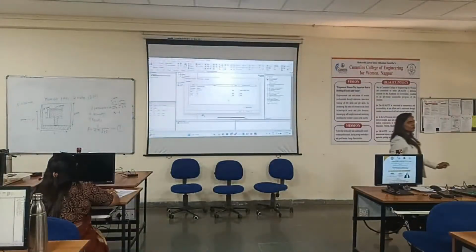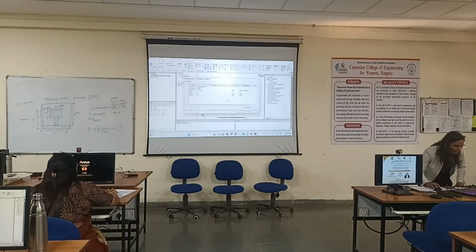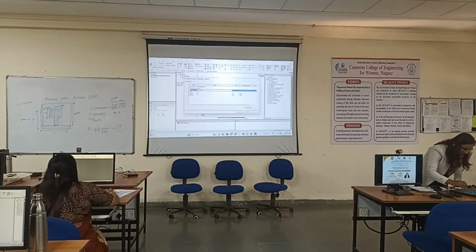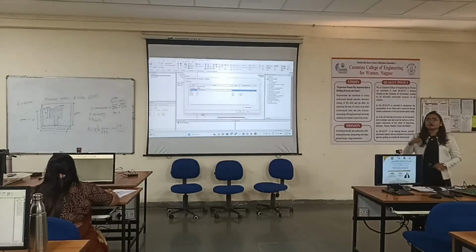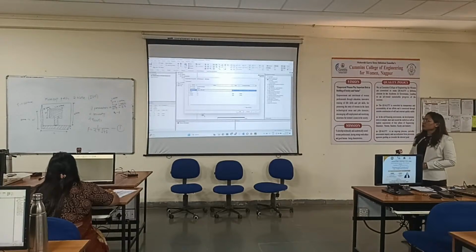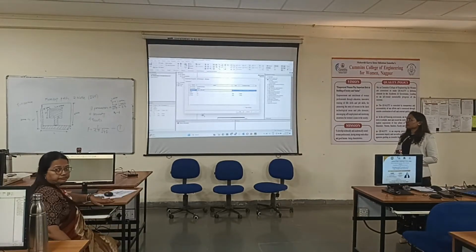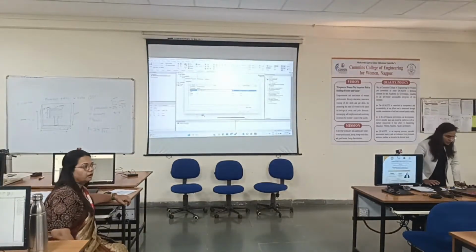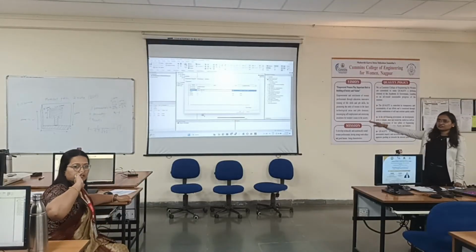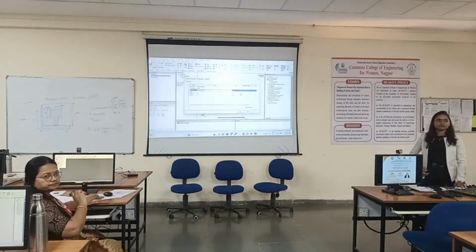Remove whatever value you have in your pop-up window. I am also going to remove it, and type there -30 mm, comma, -30 mm, comma, 0. So basically it is showing you the XYZ axis coordinate values. So -30 mm, -30 mm, comma, 0. Next one, we are along the Z axis. So in front of axis you would be able to see Z.